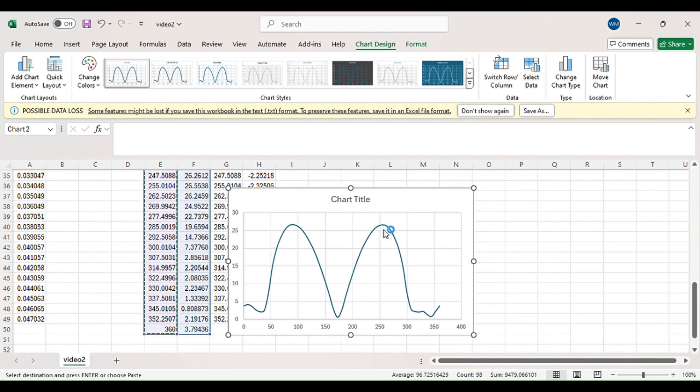After reaching the bottom of the cylinder, it moves back toward the left stagnation point, where velocity decreases, and then eventually goes near zero at approximately 360 degrees. The same errors occur due to similar reasons, because of mesh refinement errors, possibly numerical errors, or rounding errors made by Fluent. This concludes Part B of Project 2 for EAS 3810C, Design of Aerospace Experiments at UCF.